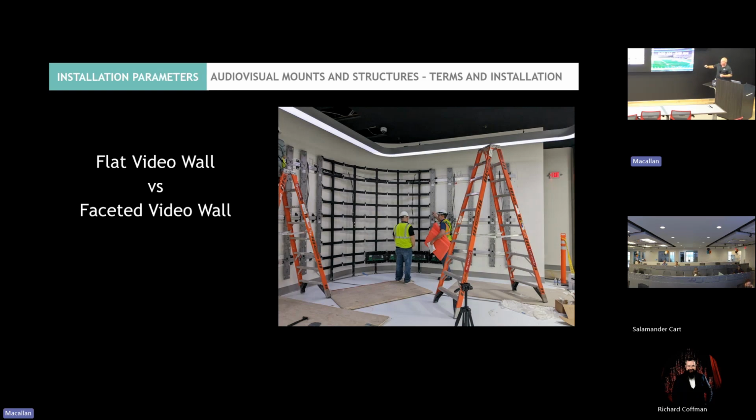Because most installs start lower left, lower right, and then you build the wall out as you go. If it's an unflat wall and you have to do a lot of adjustments, or the installer doesn't start accurately in that first corner, they could run out of adjustments at the end. So it's always important to know what we're getting into.